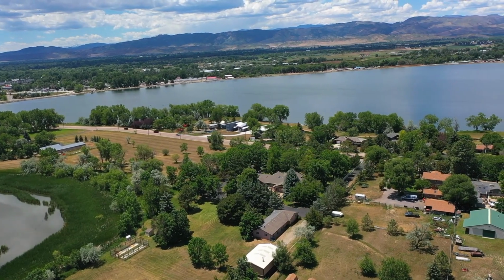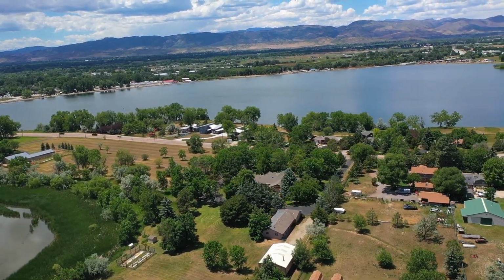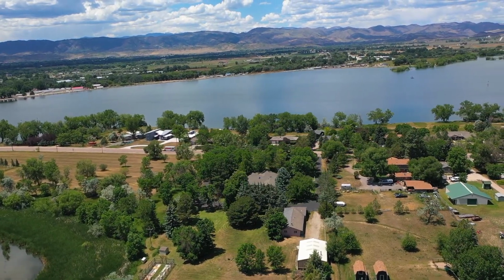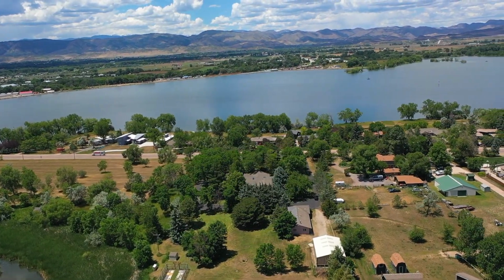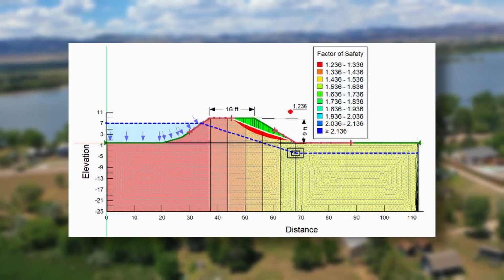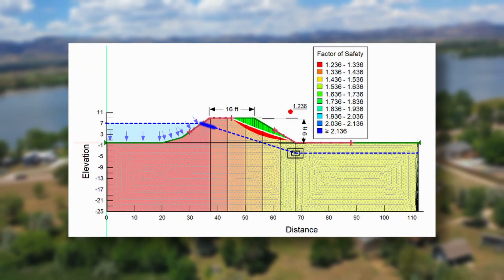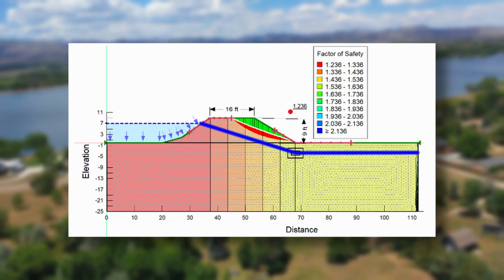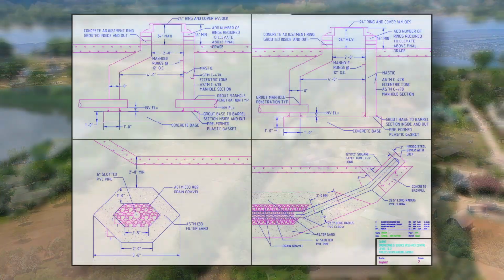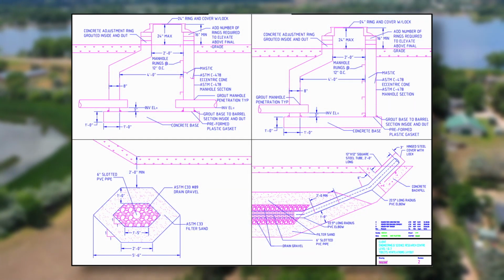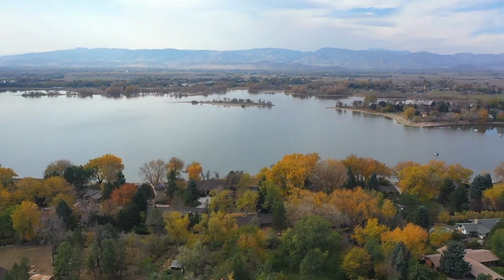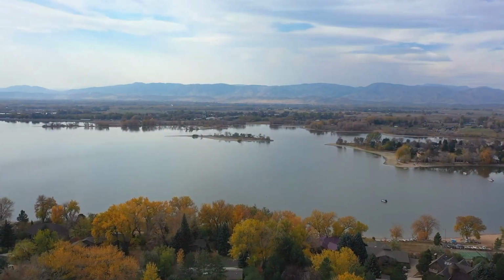Using the National Engineering Handbook, the team was able to input the parameters of the dam and obtain the candidate filter materials and the pipe sizing, resulting in a complete and effective design of the toe drain. The efficacy of the design was determined by integrating it into the geotechnical models, where it was shown that a new and acceptable piezometric surface had been realized. With this being verified, the final design of the toe drain was then modeled in AutoCAD to clearly showcase the final specifications.